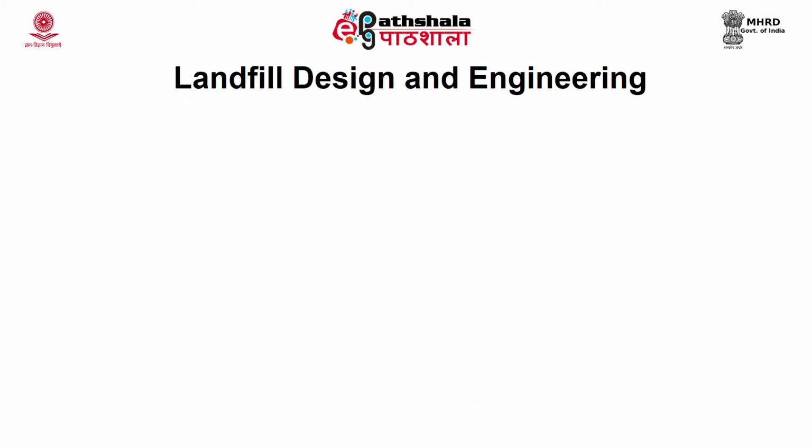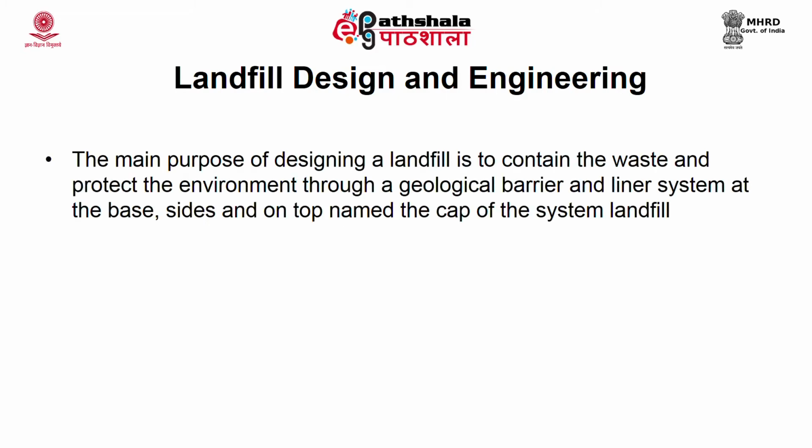Now, let us enter into the landfill design and the various engineering aspects which are involved in designing a landfill. The main purpose of designing a landfill is to contain the waste and protect the environment. This can be done by using a geological barrier and a liner system which can be laid at the base, at the sides and on top, which is termed as the cap of the landfill system.